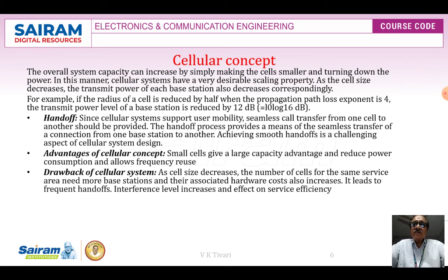So what is handoff? Since cellular systems support user mobility, seamless call transfer from one cell to another should be provided. For this, the handoff process provides seamless transfer of a connection from one base station to another. Connection means providing another channel. Achieving smooth handoff is a challenging aspect of cellular system design, and there have been many changes. It has evolved from 1G AMPS analog mobile technology to digital technology, with FDD, TDD, and CDMA technology later on. So this has changed a lot.